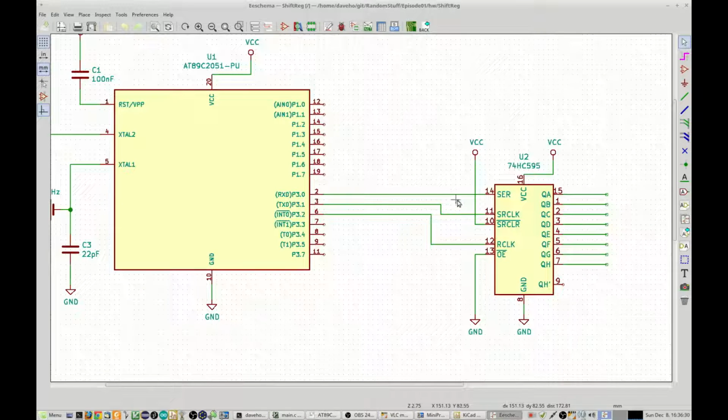All right, so very quickly, before we look at the actual circuit for the shift register demo, let me briefly explain how the shift register works. The idea is that there are 8 flip-flops arranged in a chain inside the shift register. And essentially, we can control the value of the first one by sending a 0 or a 1 here on pin 14, the serial input.